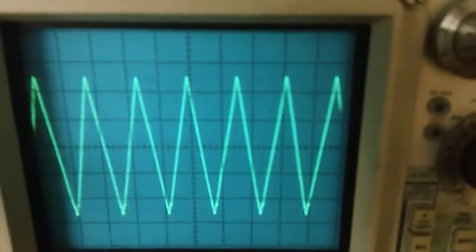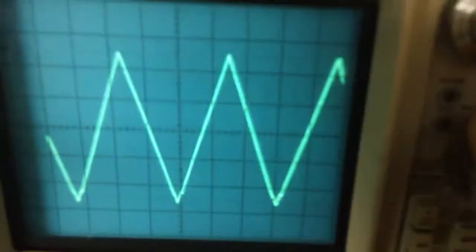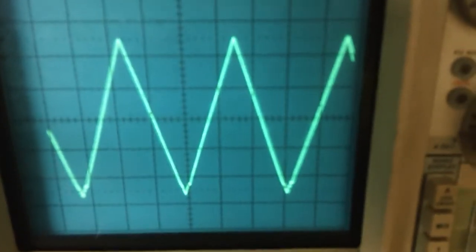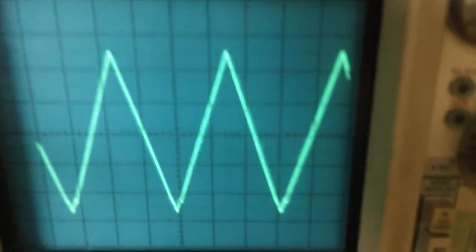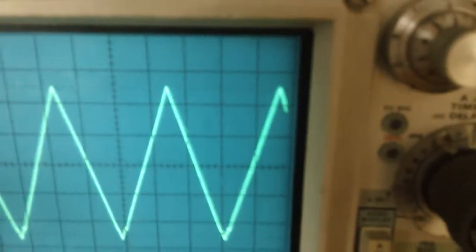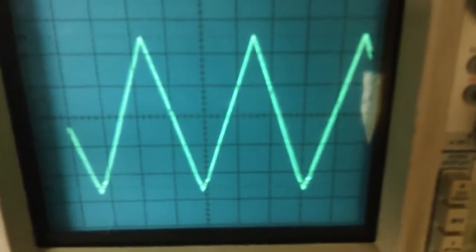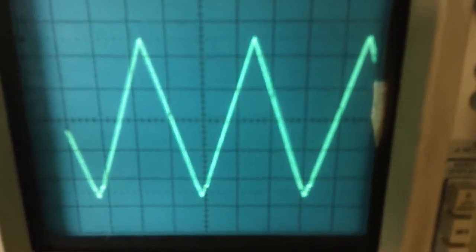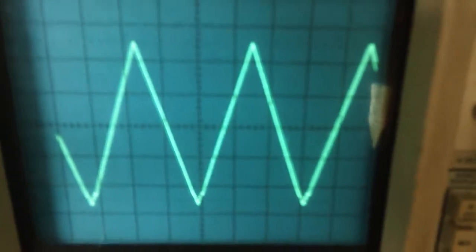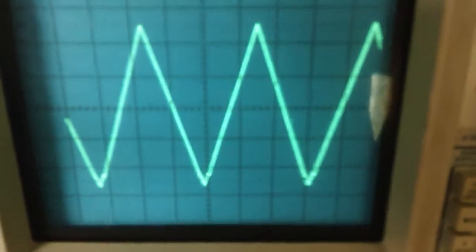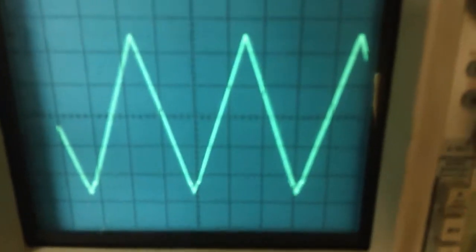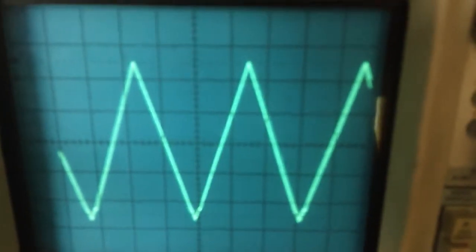The good old sawtooth. That's come out pretty nicely. Again, I can't remember the last time I used a sawtooth. I must have done, but anyway, it's there, and far easier to implement with a few resistors that cost pennies than half a dozen semiconductors. For charging a capacitor, hitting the peak, discharging it slowly, working out when you've got to the bottom and when to start charging again, it's so much easier to do with a computer and a DAC. Okay, on for the next one, eh?